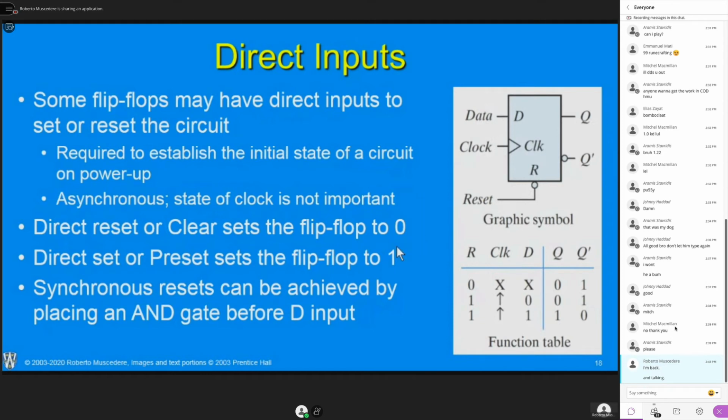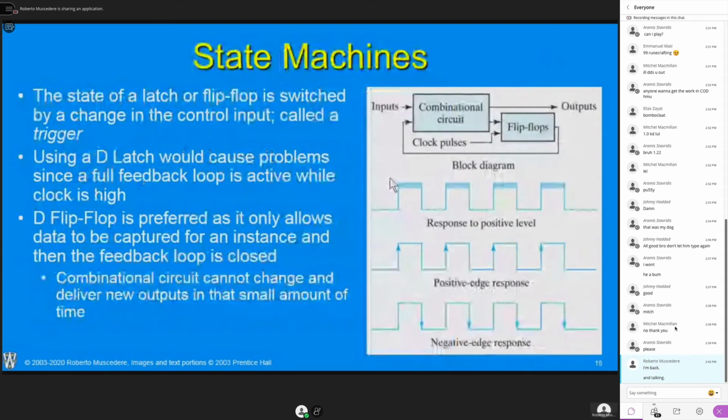We should always be aware that our circuits need to be reset. This is something you always need to do. But again, it only applies to flip-flops that really need to be reset. And again, these are usually the ones controlling our state machines. Most other flip-flops you could kind of ignore, because they don't control the data flow of your system.